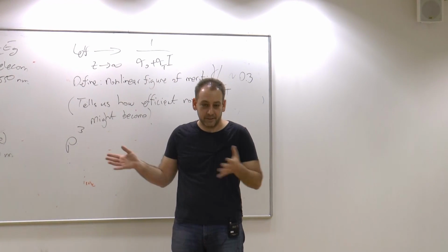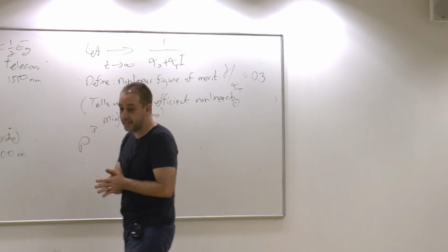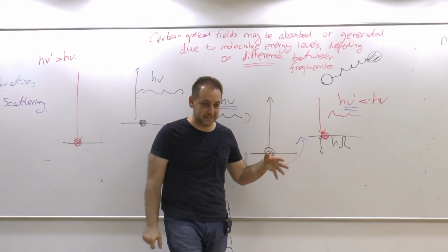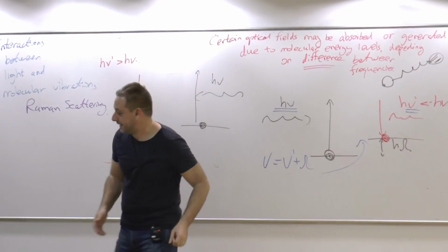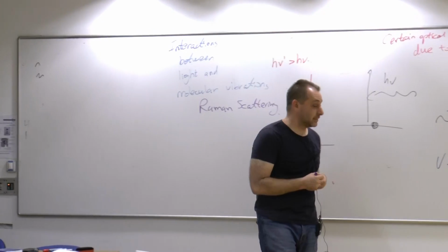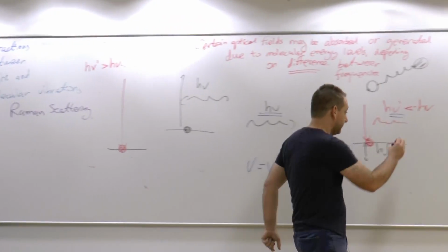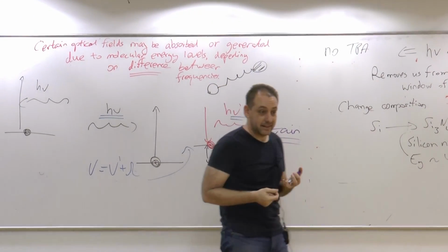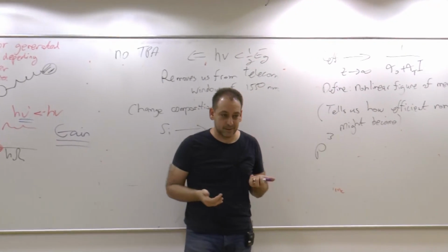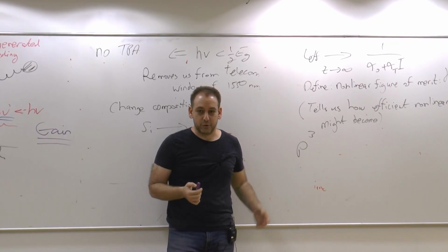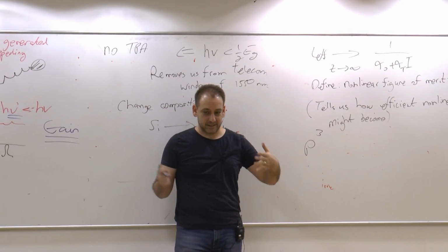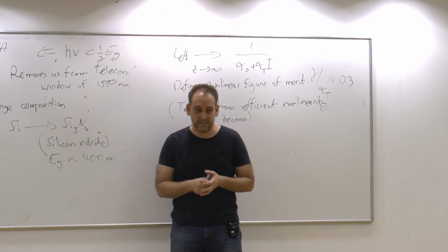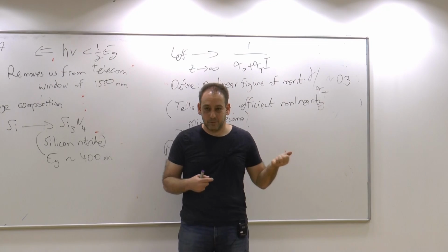And why do we care in the context of silicon photonics? Because of gain. As I illustrated to you, and again, I apologize, these are cartoons and not analysis. The analysis will come later in the year when we have the scope for it. The key word is gain. One of the main functions we need in any serious chip is amplification. Two reasons for this, very quickly. If we pick up losses over length, and sooner next week we'll have losses in couplers and losses in resonators and losses in filters. And if these accumulate, someone has to pay the bill.